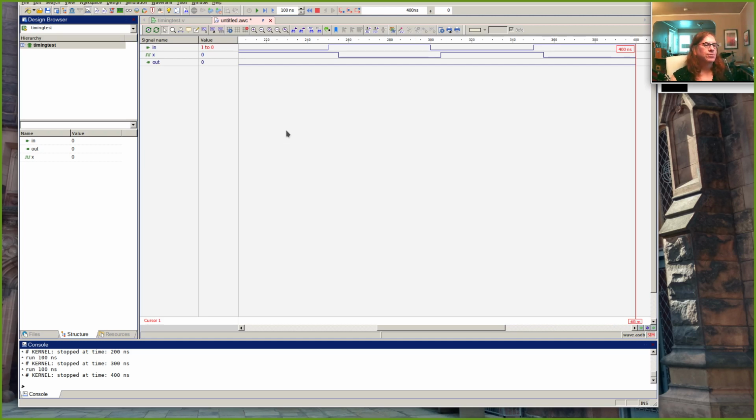Yeah, so here we've made the AND gate much slower, and it's slow enough that it doesn't actually notice that glitch in the inputs. Right, for 5 nanoseconds, both inputs are a 1, but since we changed the delay to say it's going to take 12 nanoseconds, by the time it generates an output, both of its inputs are 0.